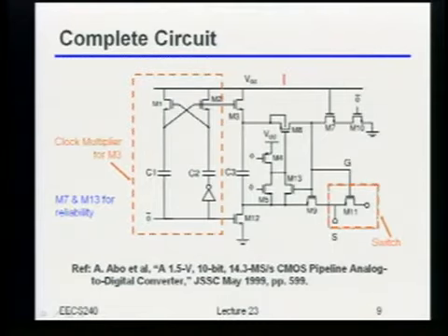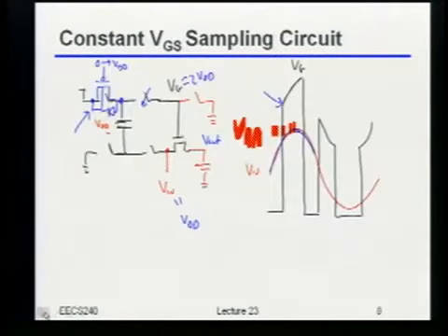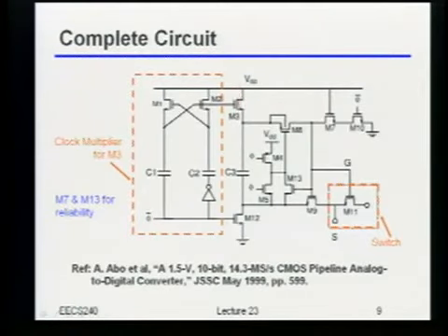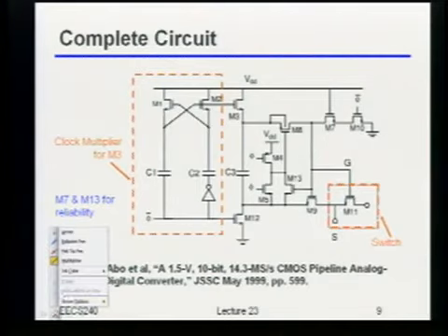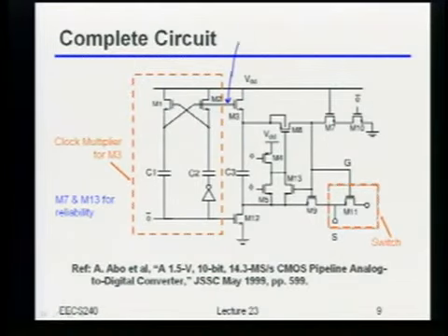So first of all, you remember I needed those 2 switches to basically charge the capacitor up to VDD? The switch that connects me to ground, that's nothing magic, that's just an NMOS transistor. But the switch that connects me to VDD on this top plate of the capacitor, I'm actually also going to build with an NMOS transistor. Because as you saw a second ago, if I used a PMOS right there and I wasn't really tricky with how I drove the gate, it would actually turn on or just not work at all because I'd be forward biasing some diode. So instead I'm using an NMOS transistor. I'm just going to be a little bit clever, because I'm going to make it so that this gate voltage right here swings from VDD up to 2 VDD.